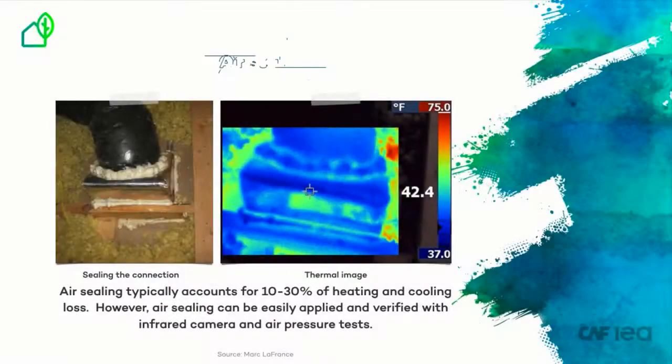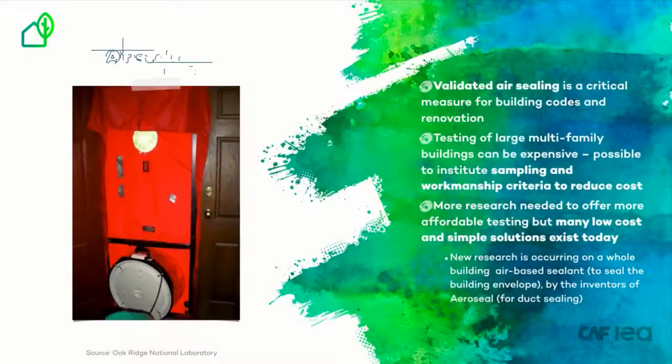Air sealing is a technique to avoid unwanted air from traveling through leaks in the building fabric or through systems such as ventilation ducts. It is easy to apply in the form of foam that expands when applied. Infrared cameras can be used to visualize the temperature distribution, finding hot or cold spots that might indicate a leak that needs sealing. The air sealing of the building envelope is measured by blowing air into a sealed opening of a building, for example through a door.